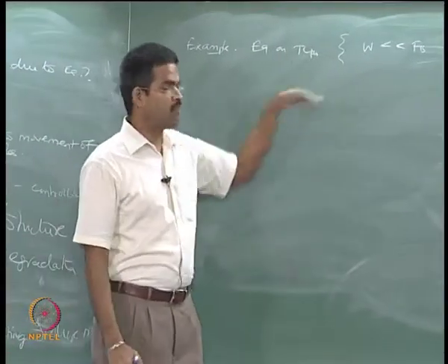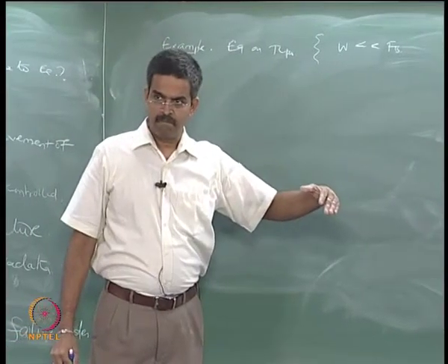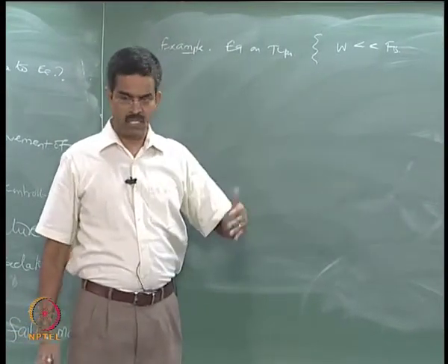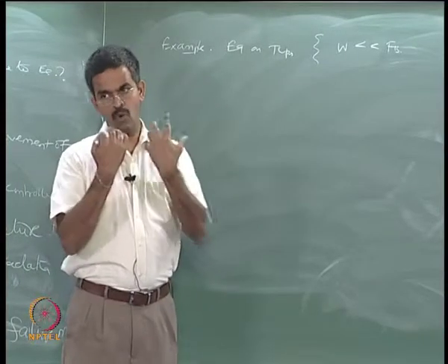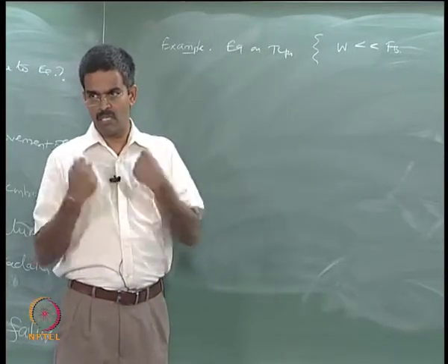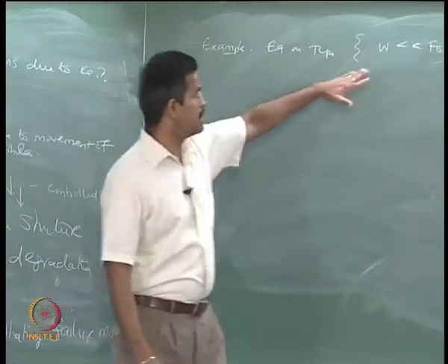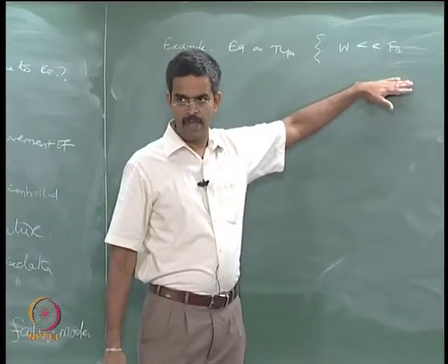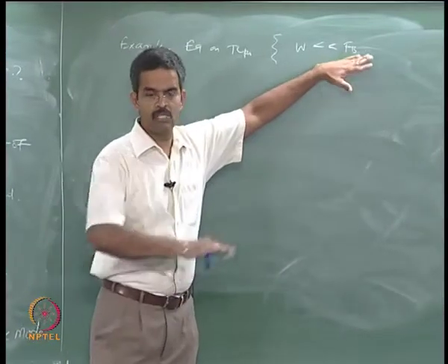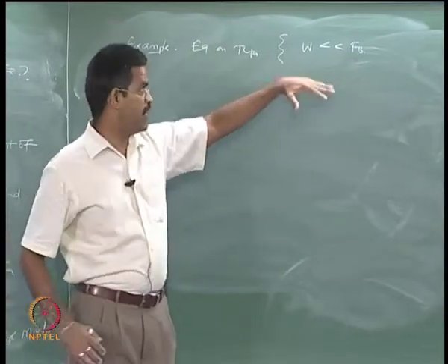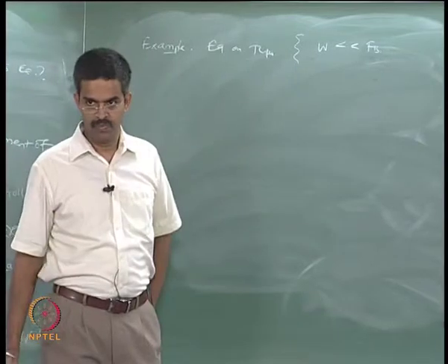That is why when you offload the structure in the sea, the buoyancy pushes the structure up. Just to hold it down you provide cables or tethers, which is why they are called tension legs. So, weight is much lower than the buoyancy. Buoyancy comes from the submerged volume, and weight is low because it is hollow.